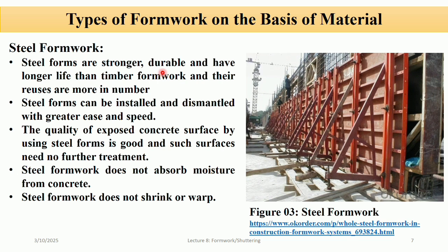Steel formwork provides a smooth, even finish to the concrete surface, reducing the need for additional finishing work. And steel formwork can be quickly assembled and disassembled, allowing for faster construction time. And steel formwork can be reused multiple times, reducing the overall cost of formwork for a project.